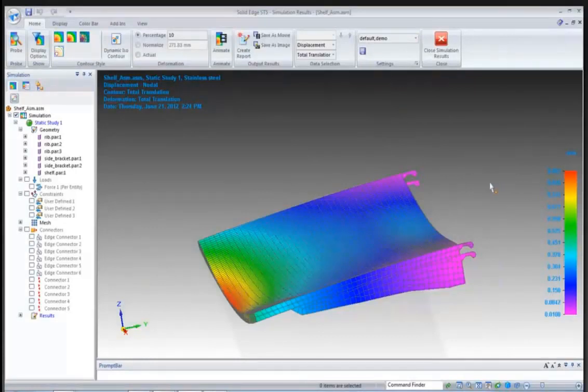So this brings me to a good point here. Because our stress is so low and our displacement is so low, remember our requirements were that it had to be less than 6 and it's under a millimeter, and our stress is really far under our yield. That's my new engineering term, really far. So what I want to bring up here is that a lot of people out there are making stuff that they've been making for years, and they're like, well, it works, it's great. Well, that's great, but you could be saving a lot of money because you've over-designed it and you don't even know it. When you under-design it, you know it because it fails. When you over-design it, you don't know.